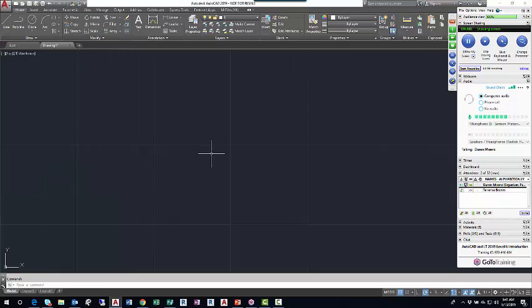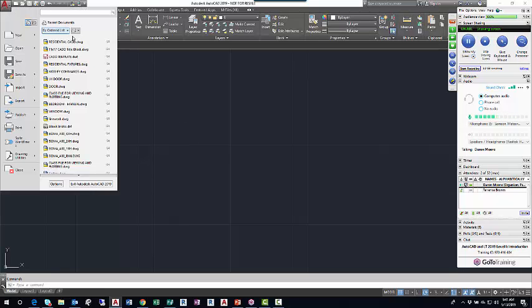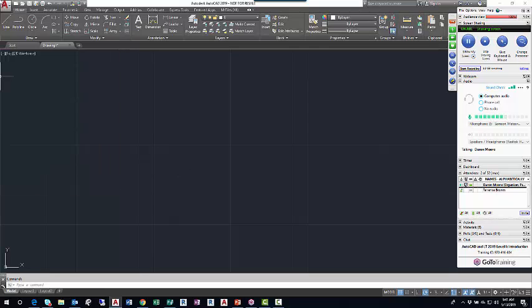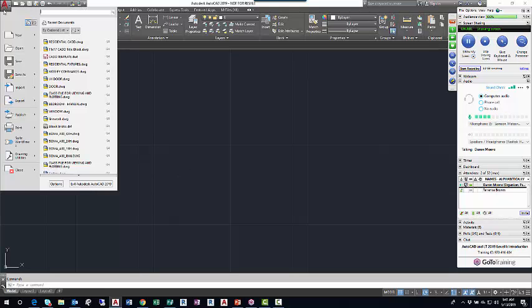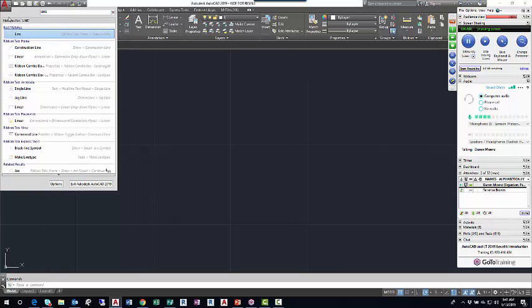There is, at the top of the application menu, a window where our cursor will flash when you first open up the application menu. It's there for a second. This would allow you to find commands. The window is actually called Find Command Location Window, and I'll type in LINE, and it's totally changed the appearance of the application menu. I am currently seeing line at the top of the list, construction line next, linear, and so forth.